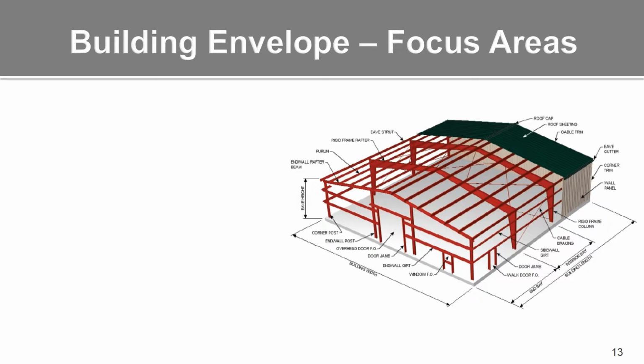As we get into the current energy codes, older energy codes always showed just a single layer of metal building insulation compressed between the metal wall panel and the girts, and maybe a single or a double layer compressed between the purlins and the roof panel. However, times have changed and the purlin and girt area has been filled. We refer to that as cavity-filled insulation.